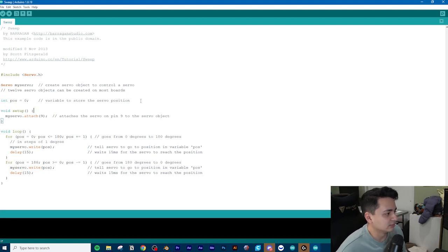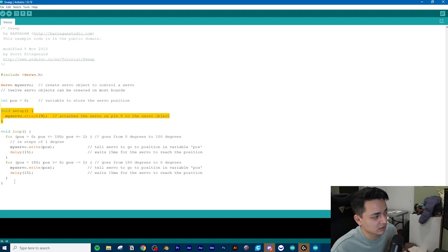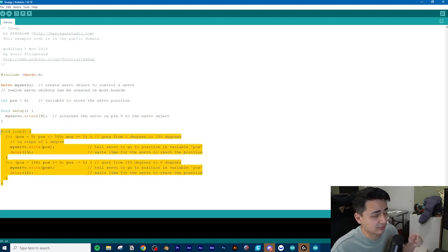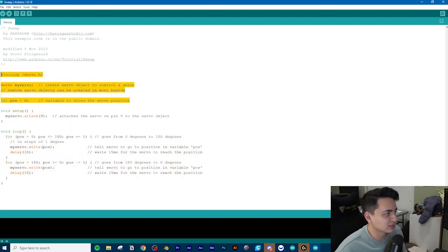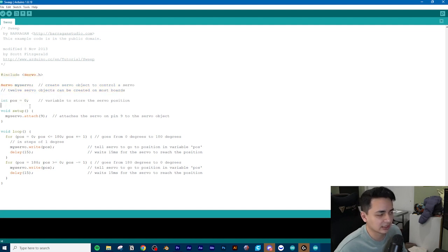And then also a little bit on what goes above the void setup. There's the void setup we talked about, which runs everything once. There's the void loop, which runs everything forever in a loop. And then sometimes there's information above. I don't know exactly the reason why, maybe this could go in void setup, but I just follow the way that the examples structure all their code, and that's how I've been writing my code ever since.